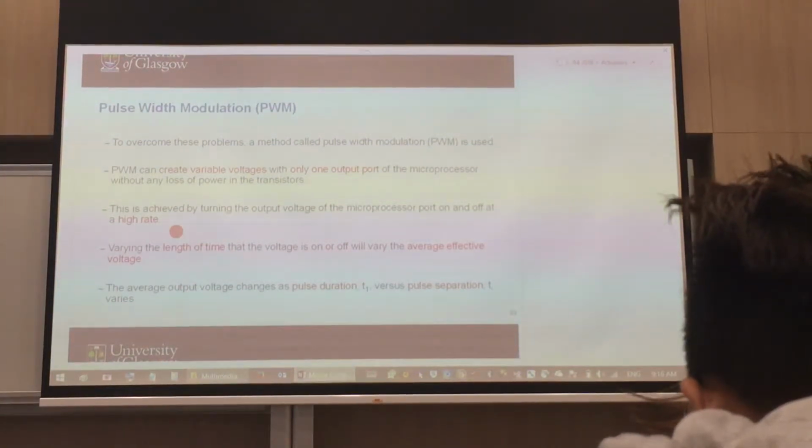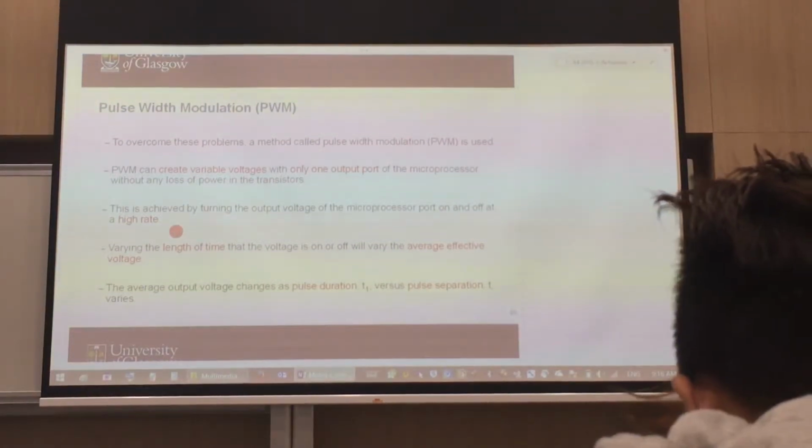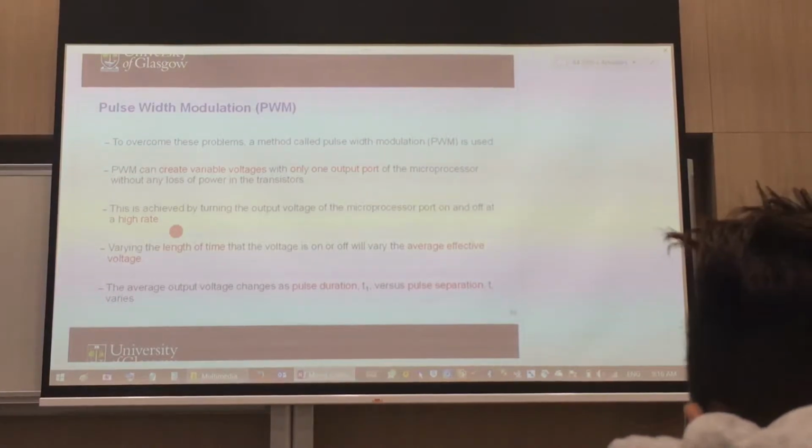The amount of power driving the light has been reduced, which means we don't need a voltage divider. We can just use this sequence of turning it on and off to control the amount of power going into our device so that we don't drive it at its maximum capacity.